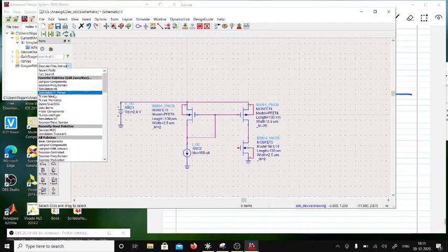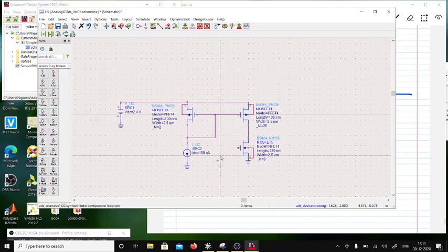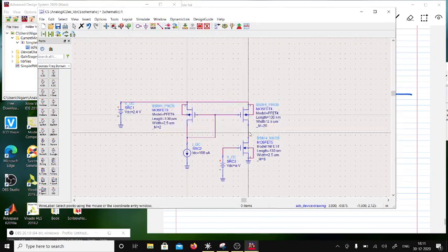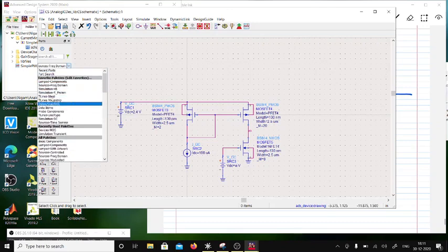Okay, so I am going to put here a DC voltage source, frequency domain DC, and I'm going to sweep this from 0 to 2.4 volts, correct? I'm going to sweep this one, which I will call VI, and this node voltage I will call VO. Sorry, I'm going to name this node VO. I want to plot VI versus VO as I sweep it, so I'm going to do a DC analysis on this.